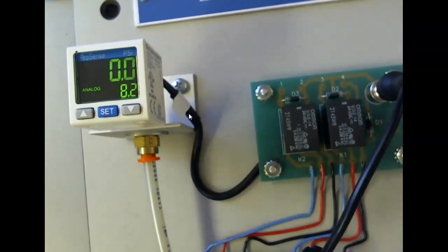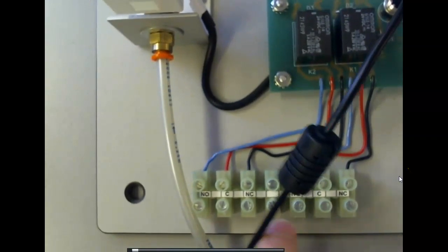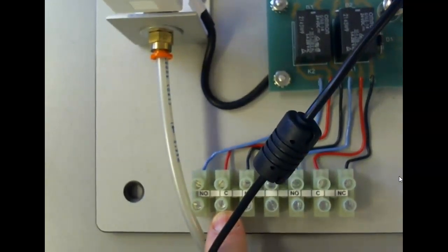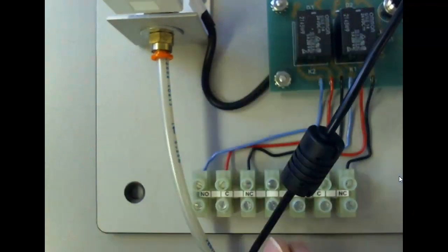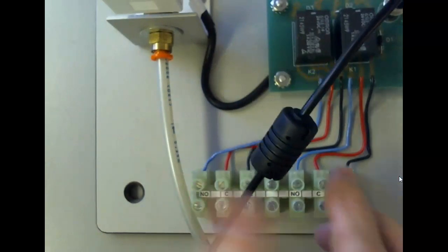And then they're bringing these over to 2 relays. So we'd have to figure out which one works for the normally closed. The relays that they have are all single pole double throw. So we have a normally closed off this one and a normally closed off that, normally open, normally closed here. Then we would have to figure out which one we want to use, and it's pretty obvious when we look down at the bottom. So it's got C, what would that be? Common. And then this would be the normally open, normally closed for this relay. And this right here, C, this would be the normally open and normally closed for this one.